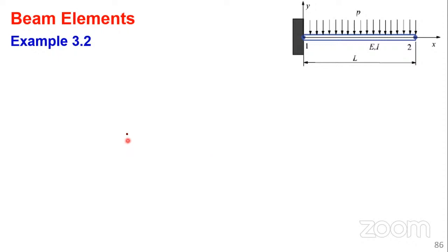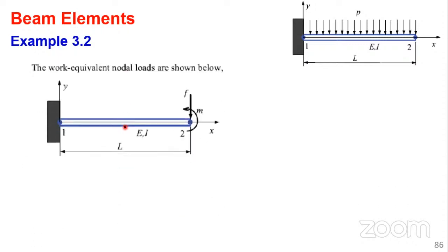Of course, for the case of the applied load, it is quite direct, because we are going to get the load here, PL over 2, half of it coming on this side, and half of it coming here at the support. So this F being PL over 2, acting in the same direction as the load, because it will produce the same effect.